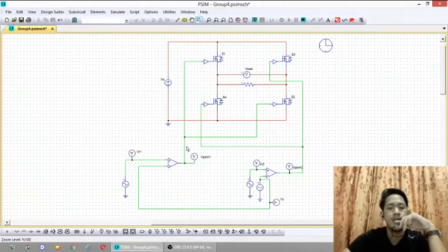this simulation diagram. The difference between the bipolar and the unipolar is that the generator uses another comparator to compare with the inverse reference waveform, which is VR. In the unipolar voltage switching, the output voltage switches between 0 and VDC, or 0 and negative VDC. This is in contrast to the bipolar switching strategy in which the output swings between VDC and negative